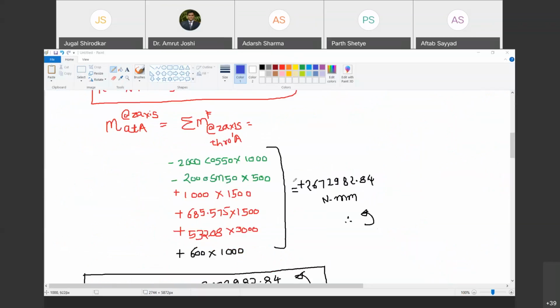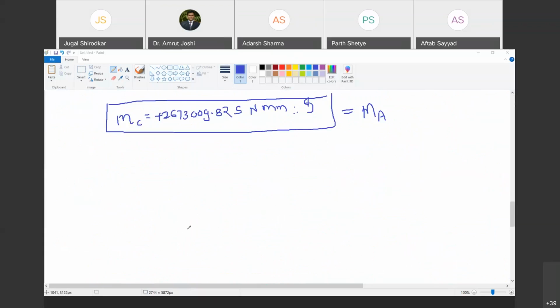Yes. So one important statement that we are going to write down now is, look, the statement before this was: on a rigid body the force can be transferred anywhere along its line of action. If the force is such, we can transfer the force anywhere along its line of action without having a different effect on the body. It will have the same effect. Are you with me? For rigid bodies. Yes, sir. This is called transmissibility of the force.